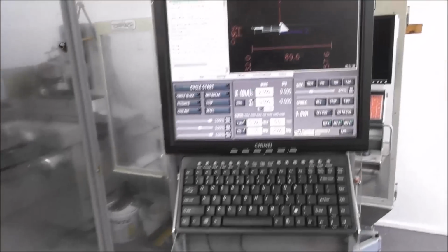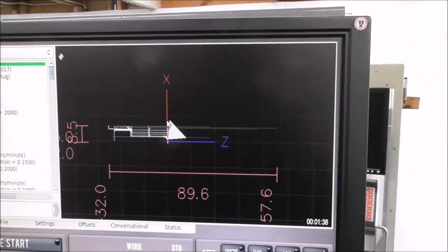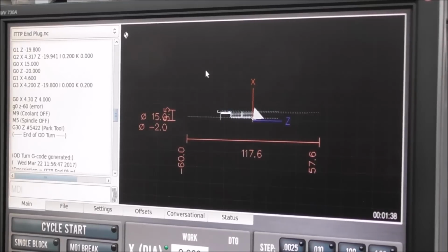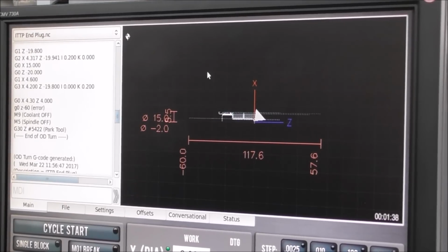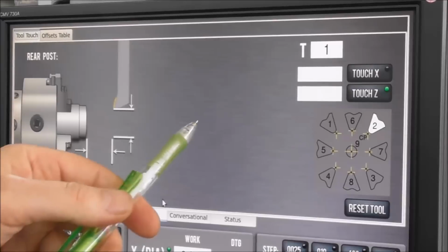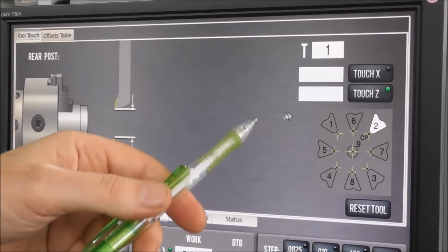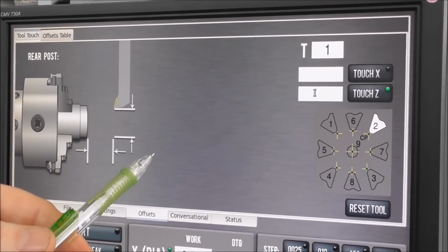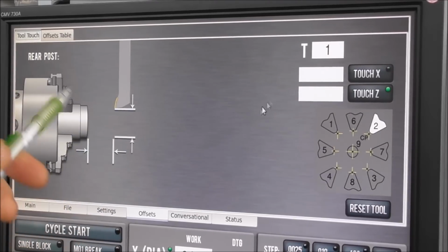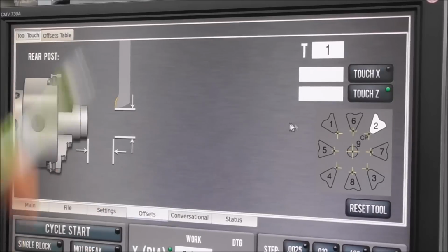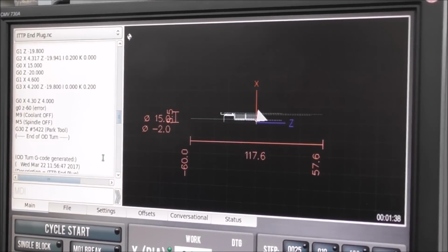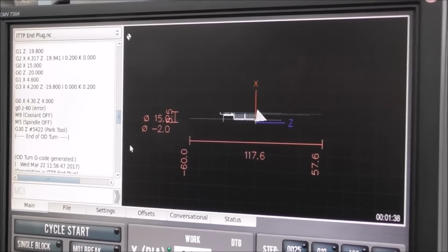Well, one thing you can do is have a look at your displayed toolpath. What's most likely to happen that will cause a crash is if you make a muck-up when you're setting up your tools. You know, when you're touching off your tools, you're entering a minus value instead of a plus value, or decimal points in the wrong place, or you've got your tools mixed up in some radical way. And what it ends up with is a rapid into the chuck, or something horrible like that.